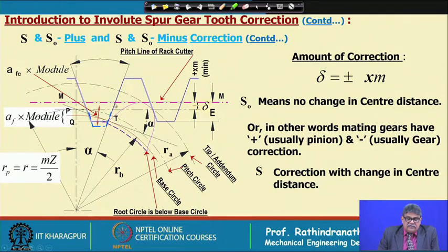So, this means that even in the withdrawn condition of the cutter, the extra amount which is the clearance amount may go inside the base circle at the first point of contact. This will give only the root, and that profile is a non-functioning profile.